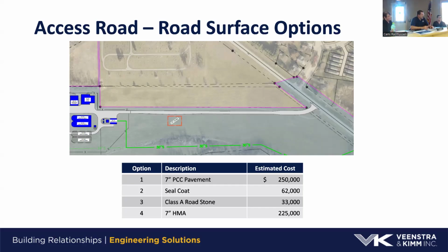And with the seal coat, knowing that we're probably storing our dump trucks and things like that, any thoughts on how long that would hold up? No, it wouldn't be high traffic, but we'd still have some heavy equipment. Yeah, and you probably have a few spots that are going to act a little differently as you plow it. Sometimes on seal coat, if you get a little bit of ridges, you tend to scalp those off. And then you have soft spots that form just from the irregularity of the soil, and you get potholes in it. So there's maintenance that's required.